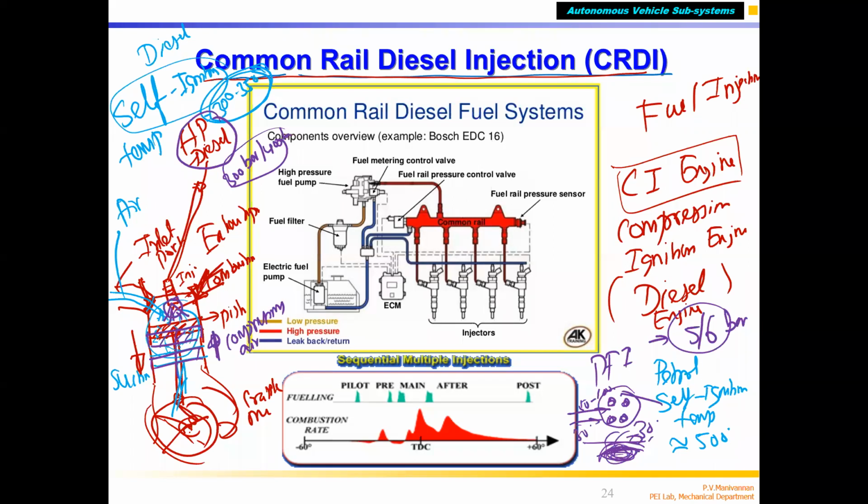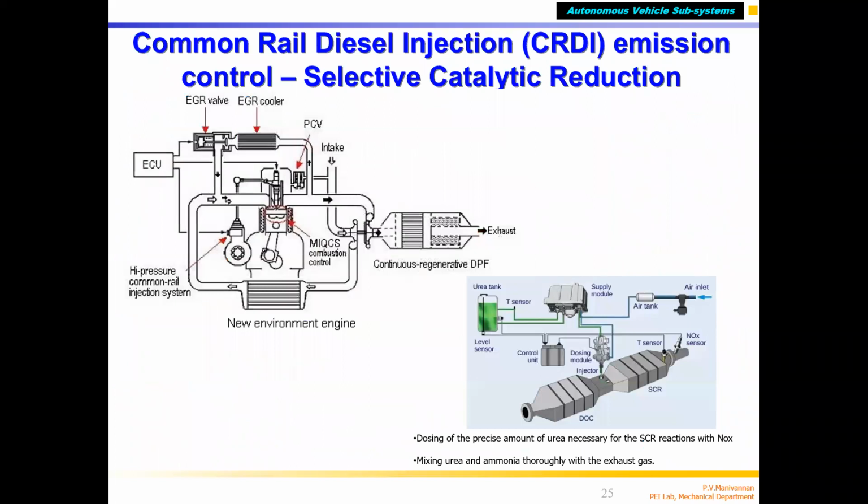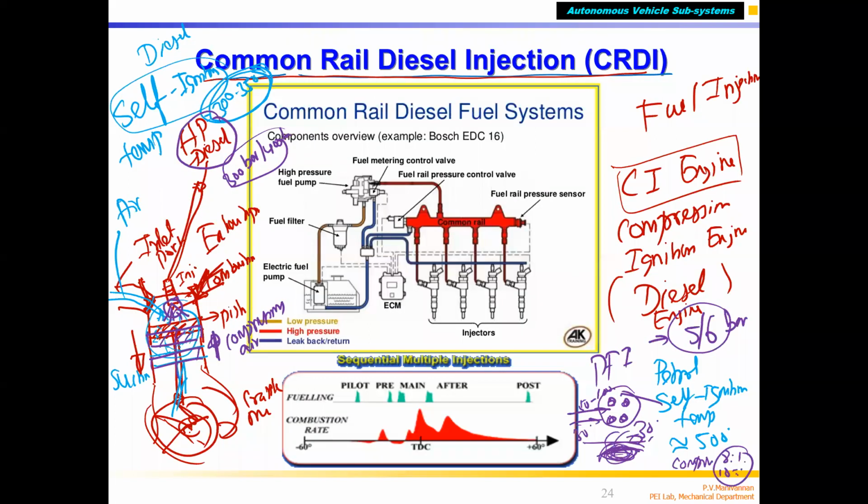Another thing is that in a petrol engine, the compression ratio is 8:1 or 10:1 only, correct? So that means at the end of the compression stroke, the temperature inside the petrol engine may be around 300 degrees, correct? Or 250, maybe 200 to 250 degrees only, not more than that, correct? Because the compression ratio is limited, the compressed fuel-air mixture reaches 200, 250 degrees.